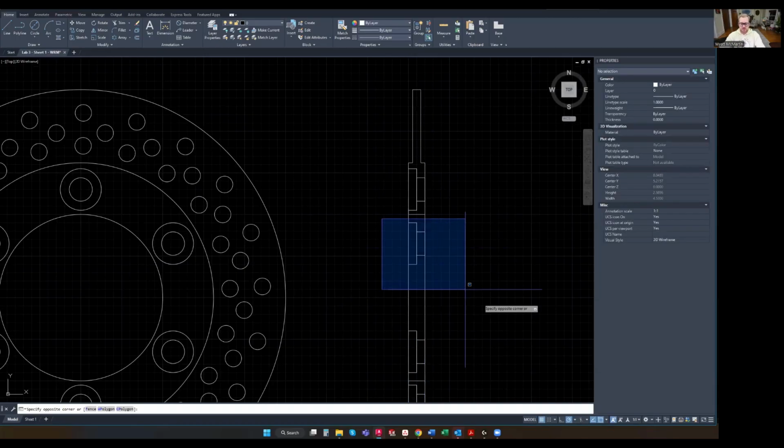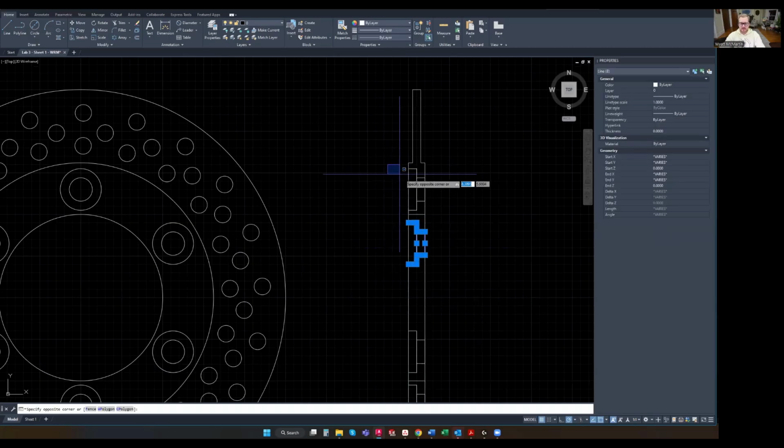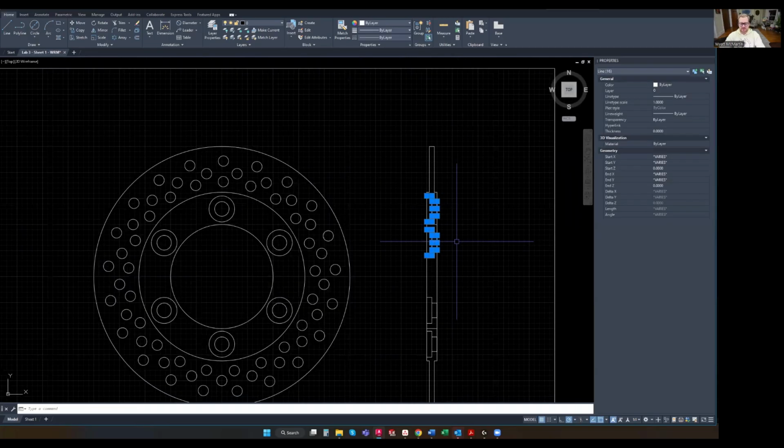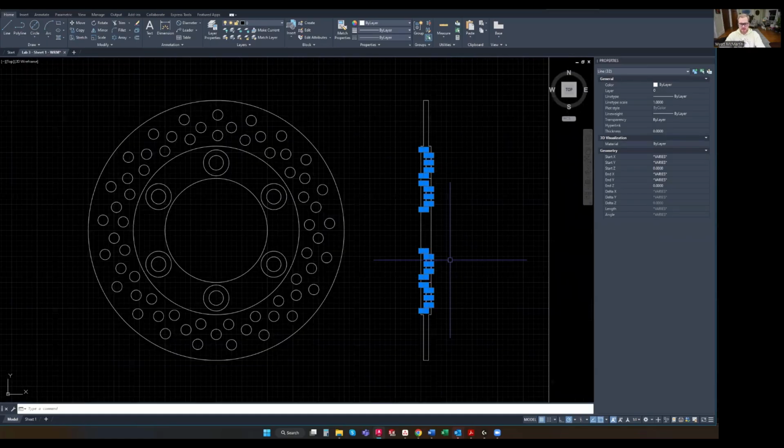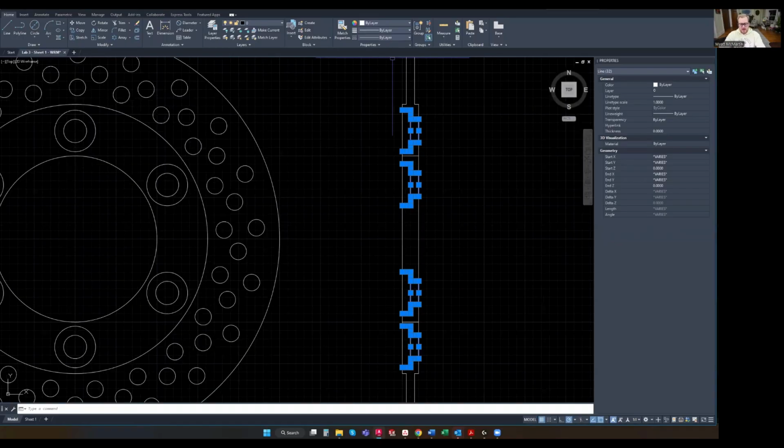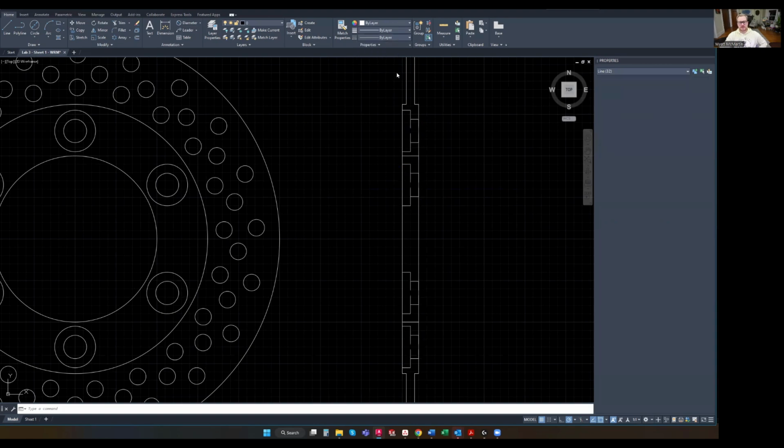Alternatively, if I use the right drag, it does not highlight anything except what I am completely encompassing with my rectangle. So that's probably the best example that we've had so far for that. Once all 4 of those counterbore pilot holes are selected, we're going to click on our line type selection up here. And those are going to be hidden2.